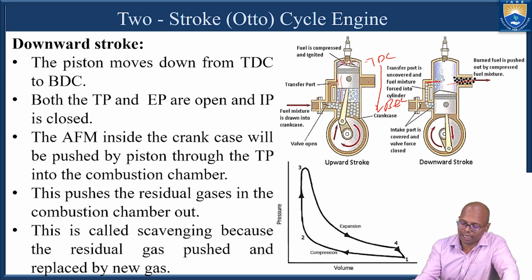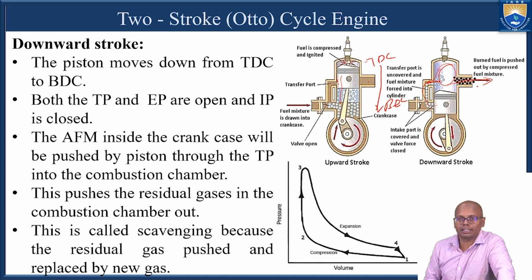At that time the air fuel mixture that is coming from the crankcase will remove the exhaust gases, and they will be thrown out of the cylinder.